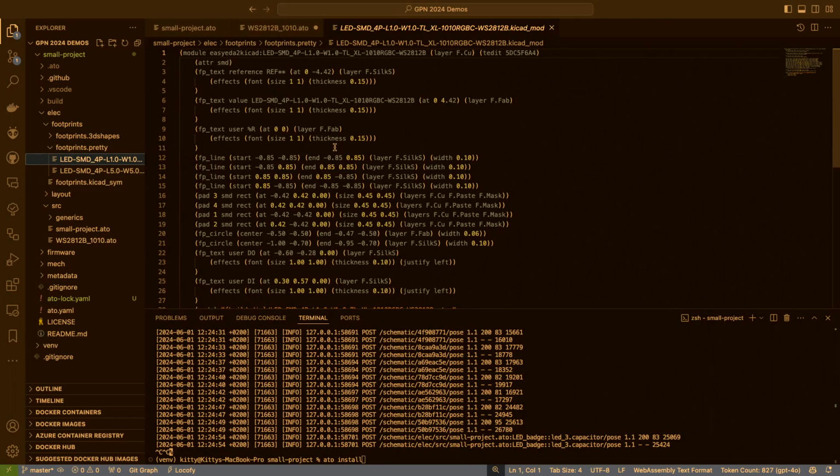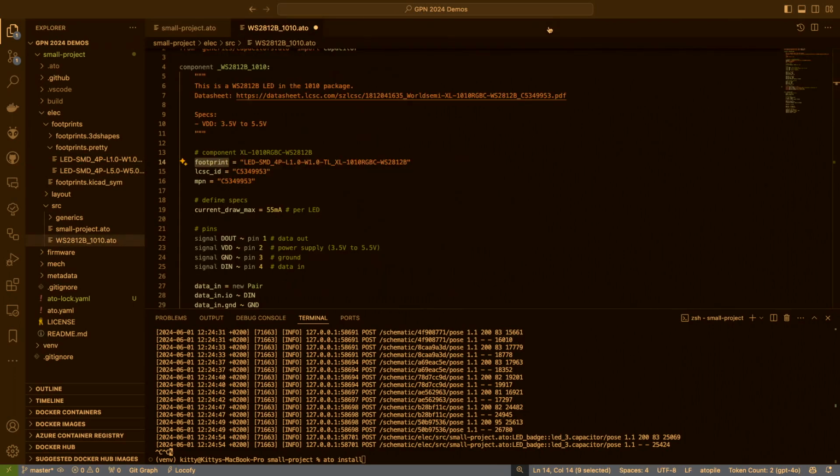So currently it's optimized for this whole KiCad workflow, but they could also extend this in the future to other software like Altium, for example. Or what you can also do is, if you create your own part in KiCad, in the footprint manager, you can export it, save it as a file, and then give it the name here, say what file name it has, and then it will automatically match that together. So option 1, download and install it from JLC PCB. Or option 2, create your own footprint in KiCad and then export it there. Yeah.